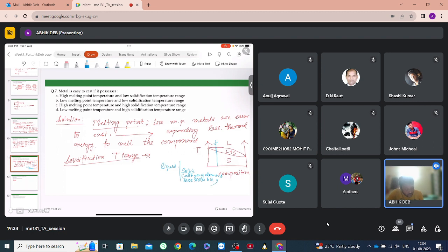So, this alloying element will start moving to the liquid region. The greater this gap, the more will be the difference in whatever fraction will be solid and whatever fraction will be liquid, and more will be this rejection. And as this alloying element gets rejected to the liquid, the composition of this liquid, initially, before any of this solidification process began, supposedly was 30% nickel and the remaining 70% is chromium.